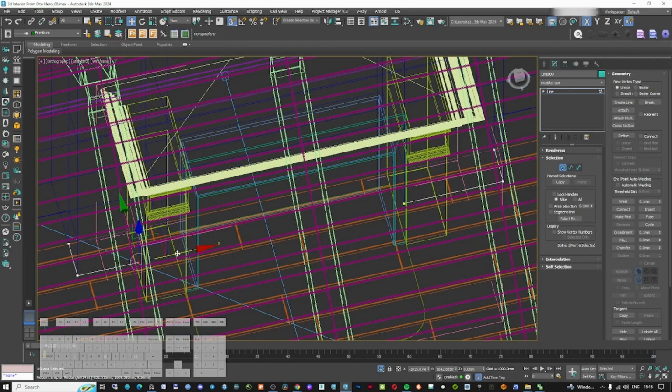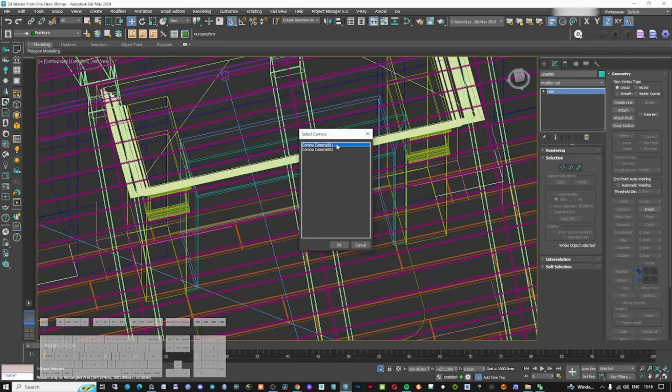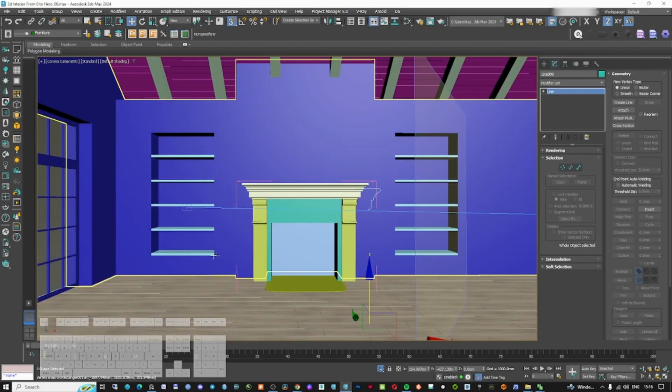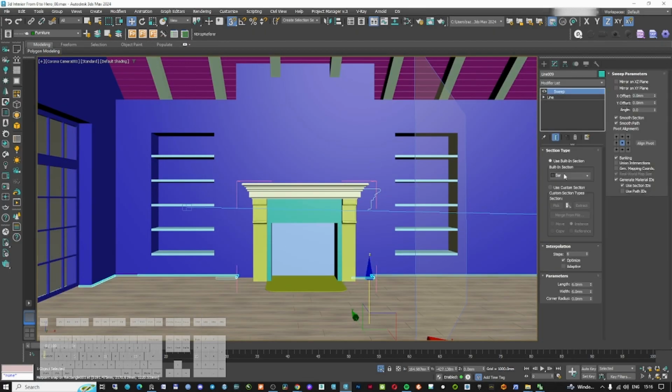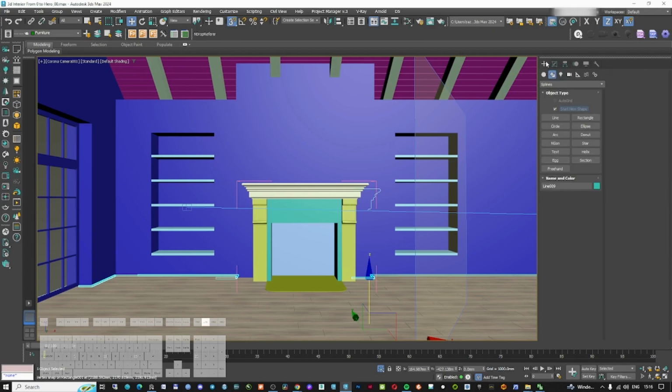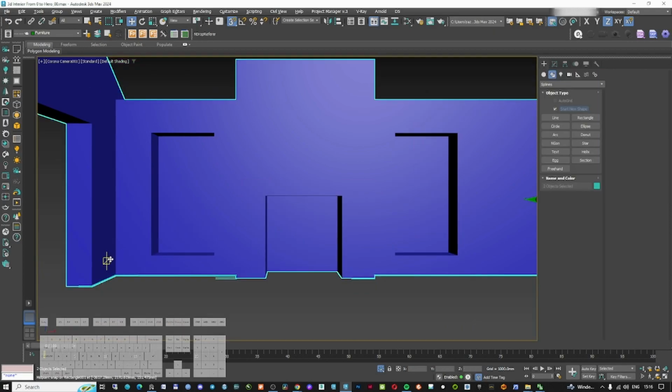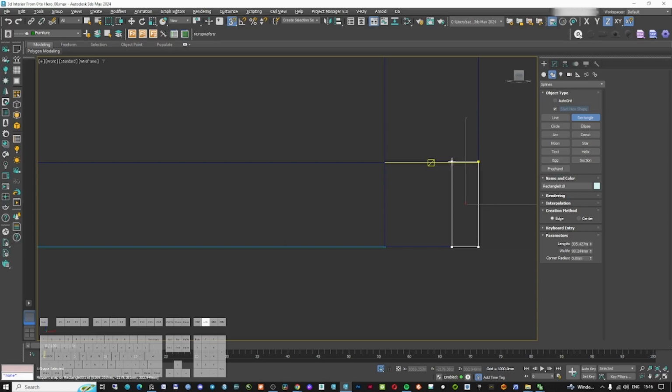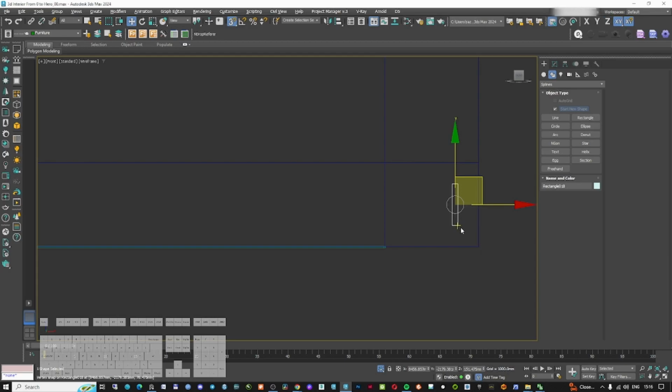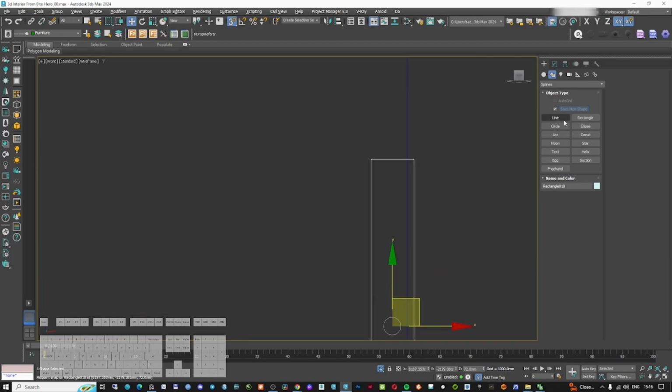And try to move all of this here. It's better to have it in 3D, of course. And yeah, we're gonna apply a sweep to this, and I'm gonna use a bar for now, but it's better to have your custom one. So I'm just going to create a nice beautiful plinth. Just gonna use a plinth of 1500, let's say. And yeah, 2 centimeters should be enough. So I'm just gonna add this here, and I'm gonna apply an editable spline to this.